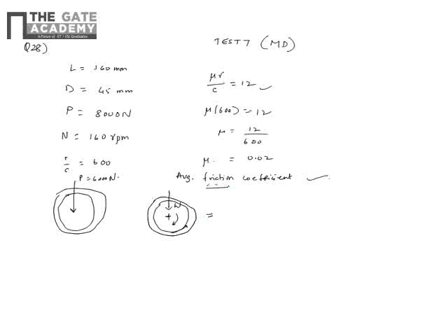So you're replacing this with a dry friction, and you know the load and you know the friction coefficient here. So the friction is mu into W. So this is the friction. Now force into velocity is the power. Friction force into velocity is the power spent against friction, or power lost due to friction. So this is the average friction force. The idea of getting a single mu value is replacing this entire hydrodynamic principle with just a single block, and basically mu W represents a dry friction synonymous with this part.